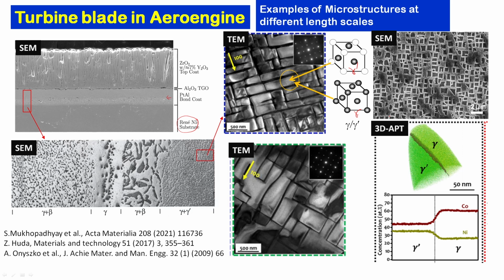But it has a different thermal expansion coefficient. Conductivity is obviously very low, of the order of 1 to 0.4 joule per meter per second Kelvin, okay, watt per meter per Kelvin. But it has a very different thermal expansion coefficient as compared to the superalloy. Superalloy is a metal, it has metallic behavior, this is an alloy of different metals. So superalloy will have very high expansion coefficients compared to ceramics.